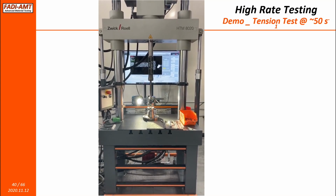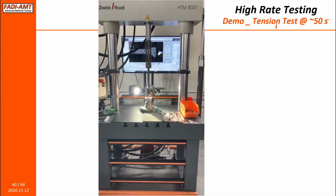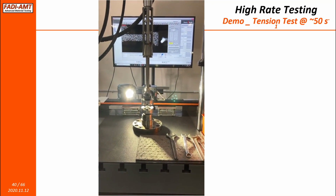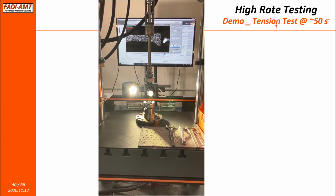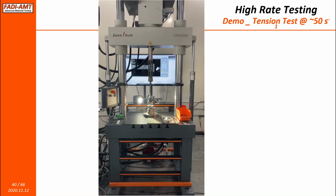The system is already configured here. The sample is already mounted, and when we start the test, the machine will try to preload the sample to detect a certain level of loading, and then after that the machine will retract downwards, and that is in order to build the right slack needed for the machine to achieve the speed that we set it to, and then after that it will impact the sample by going vertically upwards. So I'm going to replay this video again.